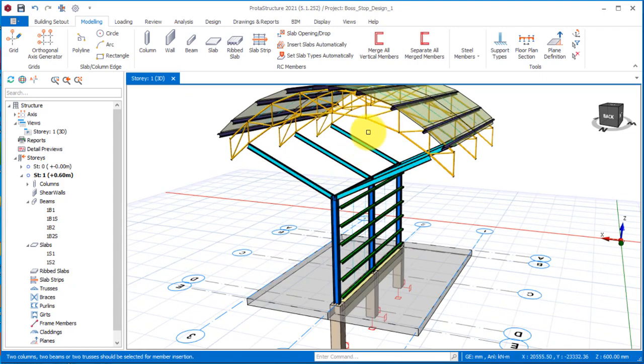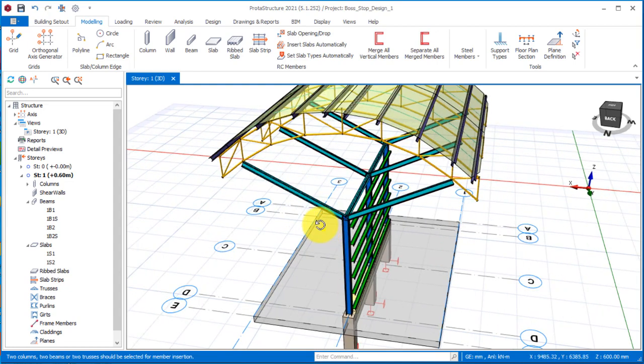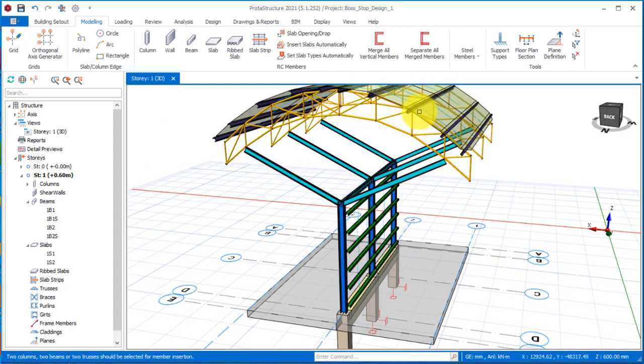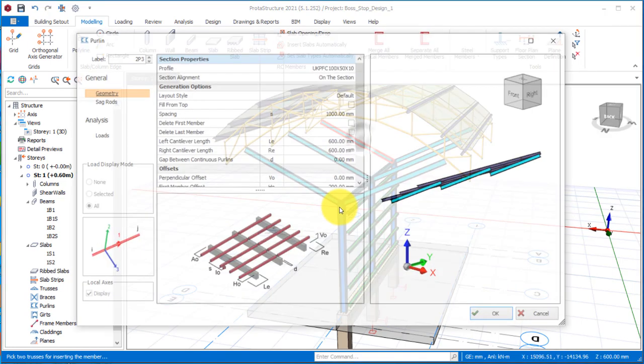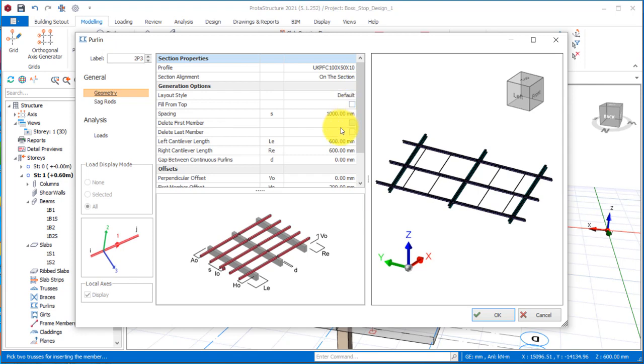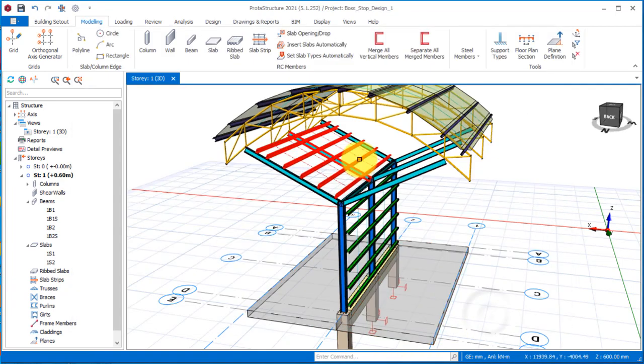Okay, so if you want to also provide maybe something like a kind of a ceiling here, all right, you can also use polines to provide that. So come to these three sections and then select polines right there. All right, once you select the poline, pick the first beam, pick the second beam, and then you have something of this kind. Okay, so you can now change the spacing of the polines. You can decide to make it 500 just like this, and then you check it the way it is. You see the polines has a cantilever, so we can choose the cantilever to be 0, 0 cantilever just like this. All right, so after which click on the OK options to get it inserted just like this.